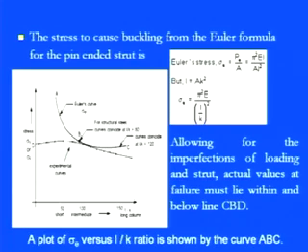So now, if you look at these points, we discussed that not only this EI and L is important, but also this radius of gyration, the L by K, the slenderness ratio, is again very important. And if stress is also a key feature apart from buckling, then if L by K is reducing, since it is in the square term and in the denominator, you can see that sigma E is increasing drastically.